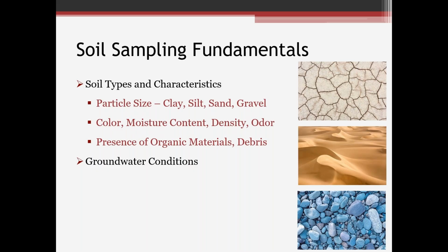But looking at moisture content, again, groundwater conditions, those may help to transport contaminants along the site, on the site, or even off the site. So it's definitely important to know whether we're dealing with a situation where we have soil above or below the groundwater table. So that helps guide some investigation and remediation planning. Not that we're going to get too much into groundwater here, but just knowing that will help direct some of that field investigation for soil sampling.